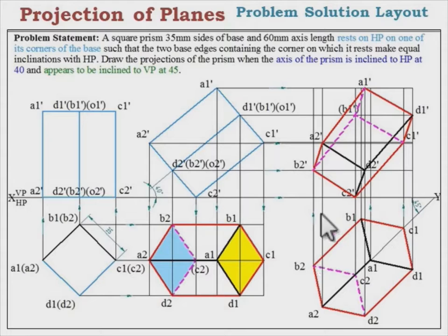We will draw the vertical projections from this top view and horizontal projections from the front view and mark the points as discussed. All outer boundary points are marked with continuous thick line. Next step, since this is the direction to view the front view for this position, the face enclosed with A2, B2, C2, D2 is visible.